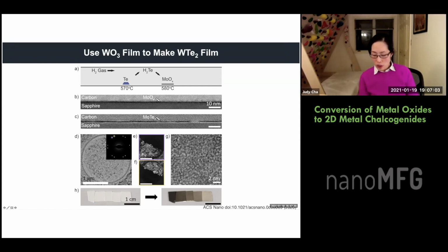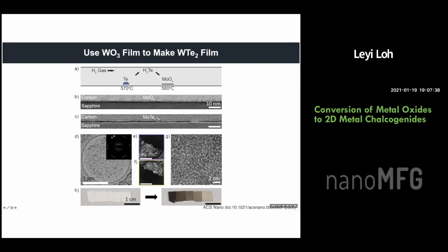Thanks for the question. When we sputter deposit the metal films on silicon oxide and then convert them into the vertically standing TMDs, as long as we dip the whole substrate into either HF or KOH, the film floats up. Whether it's more difficult or not in terms of energetics, we don't know, but in the lab it seems pretty straightforward and we don't have much difficulty. Okay, thank you very much.